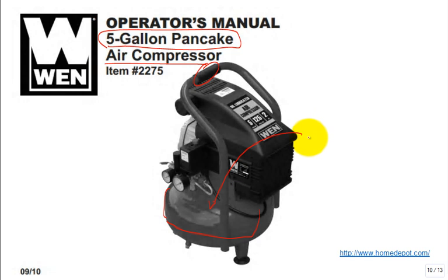That air had some humidity in it. And now that water does something funny. At first, when it dumps it into the tank, it's hot air. But you let that air sit overnight or just a couple hours, it's cooling, it gets to the same temperature as the room. But it's at high pressure. You can take the tools in this class, and we'll do that, and show that it cannot hold as much moisture. So even though the air out here may be 50% relative humidity, when you pressurize it, put it in a tank, it's hot, that's fine, it's not going to have a problem with humidity then. But if you let it sit in a tank and cool under high pressure, it will become saturated air. Some of that water vapor will condense.